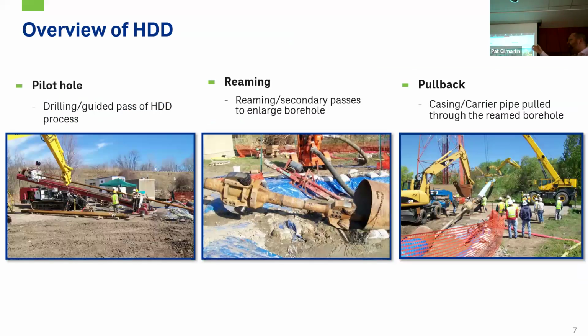So just a couple pictures of those different processes. So the pilot hole drill right here, you can see your HDD equipment with your drill rig, your drill rods, and your crews working on that side. For the reaming passes, you can see here these reamers. These are called barrel reamers, where you get the drilling mud coming through those reamers, and those are meant to enlarge the borehole. There are various different setups for whether you're doing soil and rock.